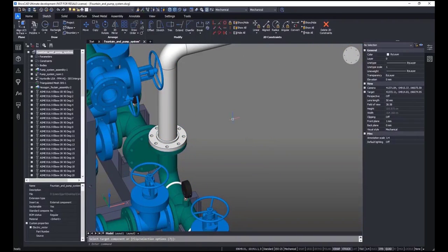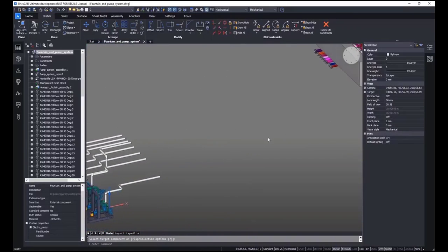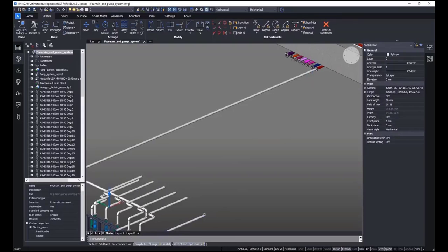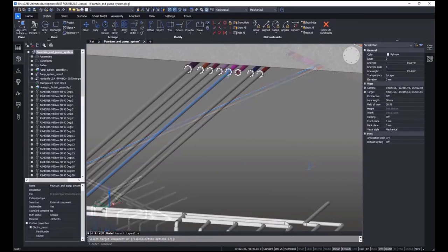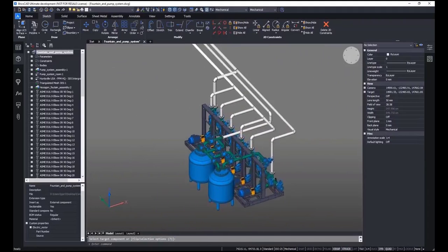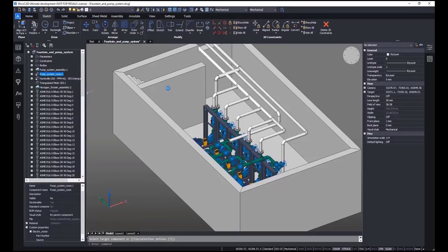But if we have to connect parts inserted previously, we can use the BM connect command. Similarly to BM insert, it properly resizes the connecting parts and generates assembly constraints for them. So you can see how piping parts are automatically resized and moved to the appropriate positions. Note that pairwise connectivity between piping parts is not broken after this operation. Imagine the amount of work needed to create the same model with manual manipulations.